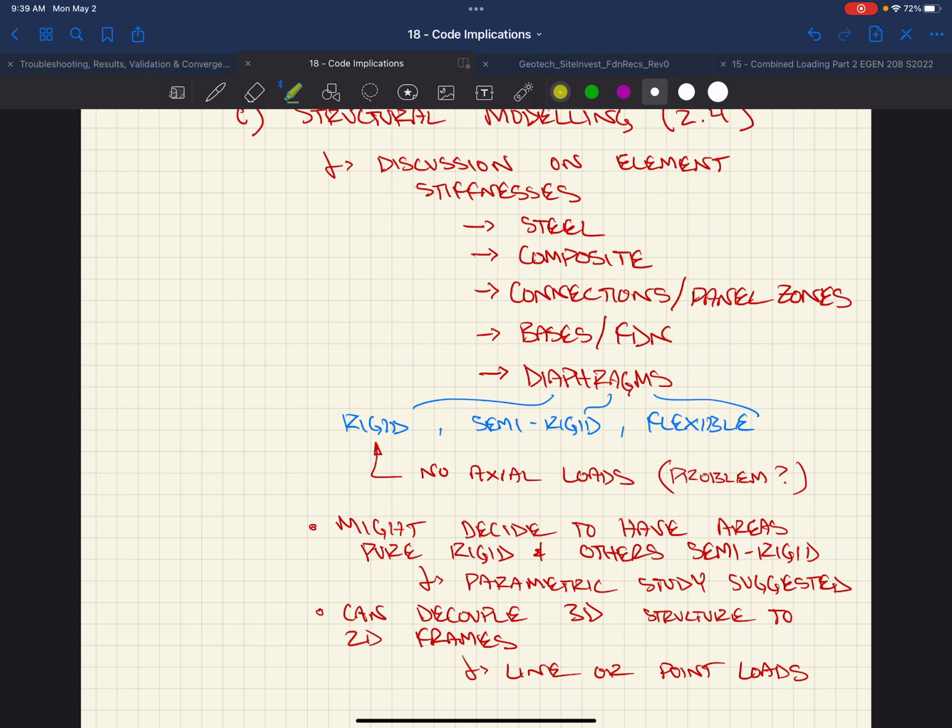Right, so you got this steel beam, got this headed anchor stud, and all of a sudden you got this, oh, that was nice. Do this. Okay, got this metal deck that's sitting on here. Then you got this concrete sitting on top of it. Well, when you're in positive bending, this is in compression, that's going to stay together. You're going to have some nice stiffness associated with that. If it's a negative bending though, all of a sudden this thing becomes in tension, starts cracking apart, it's not really going to do anything for you. You might just have the stiffness of the steel beam.